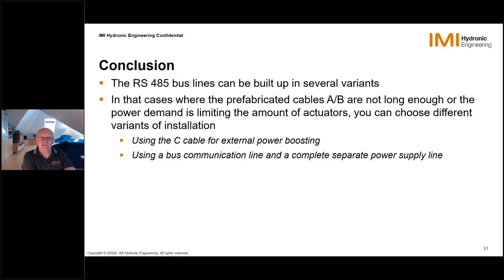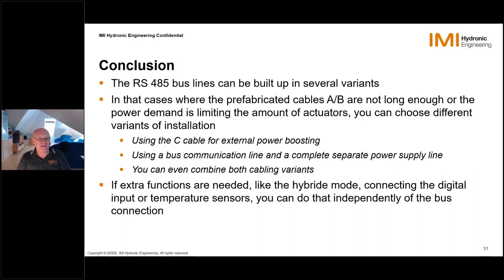We can separate the power supply line from the bus communication line. It's very often done. And we can, as we have seen before, combine our cabling variants in a different way. And of course, still, always, if you need extra functions like the hybrid mode, or to connect the digital input, or to connect the temperature sensors, then you can do this independently of the bus connections. So it's not directly interconnected to make these things.